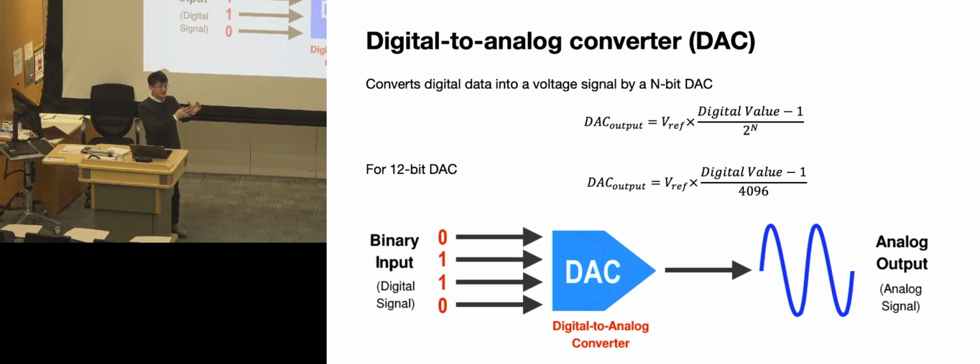In practice, it doesn't add any value. It doesn't have practical value to consider that 1 step, because in the hardware configuration, that's basically your error range. It could be within that anyway. Imagine you have a resistor with plus or minus 1% error tolerance, then it could be anywhere there. If you hang up on that 1 bit, it doesn't make much practical sense. We could do that, but this is just how people do it nowadays, because we indeed have 2 to the n values with n bits, and you have 2 to the power of n minus 1 steps in between. So that's just how people do this nowadays. Hope that answers the question.